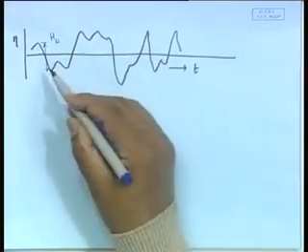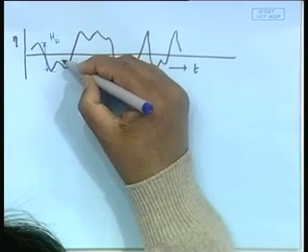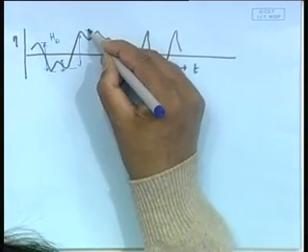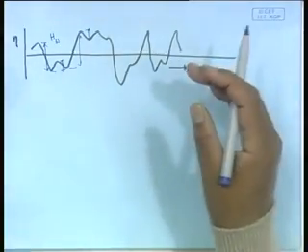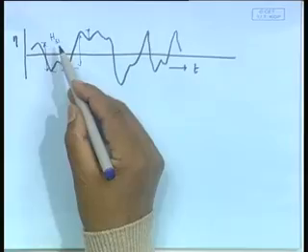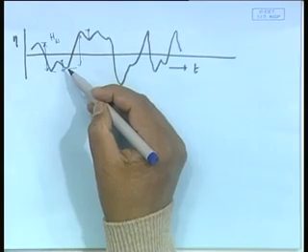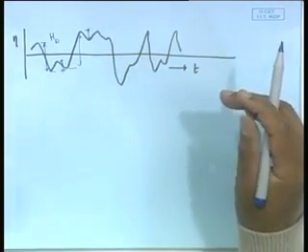Now you take a long signal and measure all these crest to trough heights, etc. What would happen? You are going to find that this HW, which I am defining as crest to trough or trough to crest, peak to peak, you may say, has a whole lot of occurrences. Like you will find the first record shows 3.1, next one shows 2.1, next one shows 3.0, etc. So you are going to get a whole lot of random records of heights.